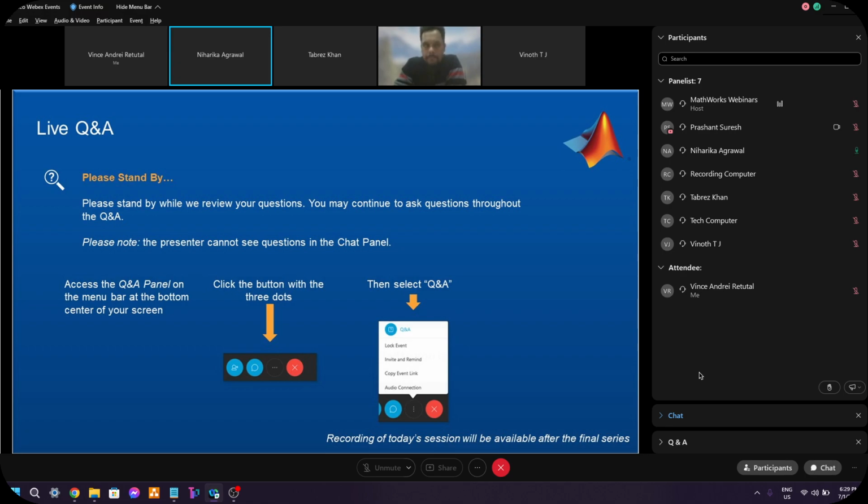The next common question from customers is: do we also support pre-handwritten RTL code for co-simulation? Yes, we support pre-existing HDL code by using Cosimulation Wizard. It's an app, a GUI for the co-simulation part, where you can import your VHDL code directly, apply all the constraints and the clock frequency, and generate a co-simulation model. You can then verify your design with that co-simulation model.